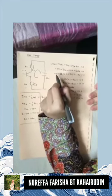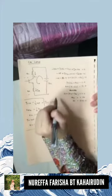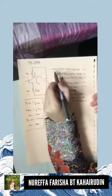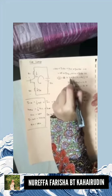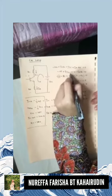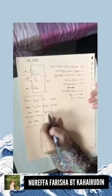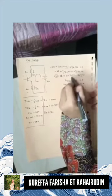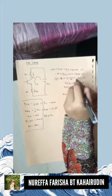Okay, put in the values of VCC and VCE that we got. So VCC is 25 volt and VCE is 12.5 volt, and ICRC plus IERE. So IC and IE are equal, so I combine to IC only, times RC plus RE.